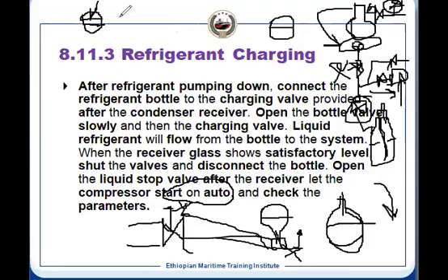It means when you pump down, it will be slightly higher than the 50%. Usually it is that way. So when you start the system, it will be maintaining within the sight glass, half or slightly lower than. So that way you will have to maintain. But it should not happen that after pumping down you see the level in the sight glass, and after that, when you are running, there is no level. There has to be also a level. Clear, Melissa? Yes, Chief, it's clear.